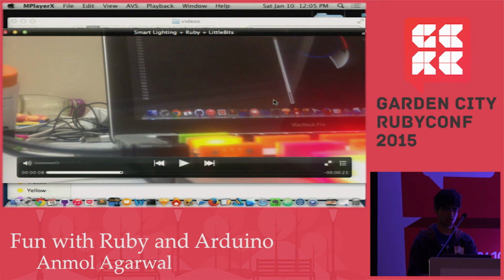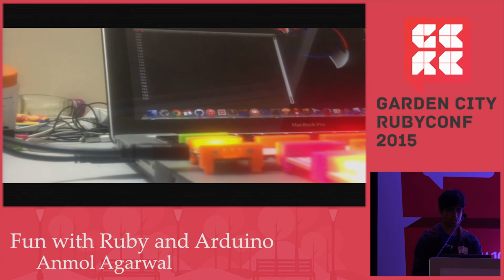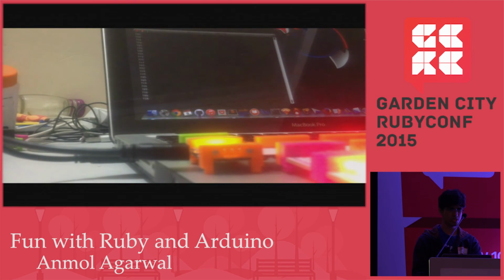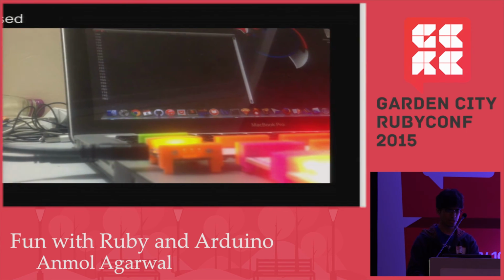Right now lights are on, and the value you can see in the terminal is like 790 or something, 3 digits. But if I turn off the lights, the LED turns on automatically, and you can see the value is 1022, 4 digits. So you could really see the change in the value. So that's cool stuff.